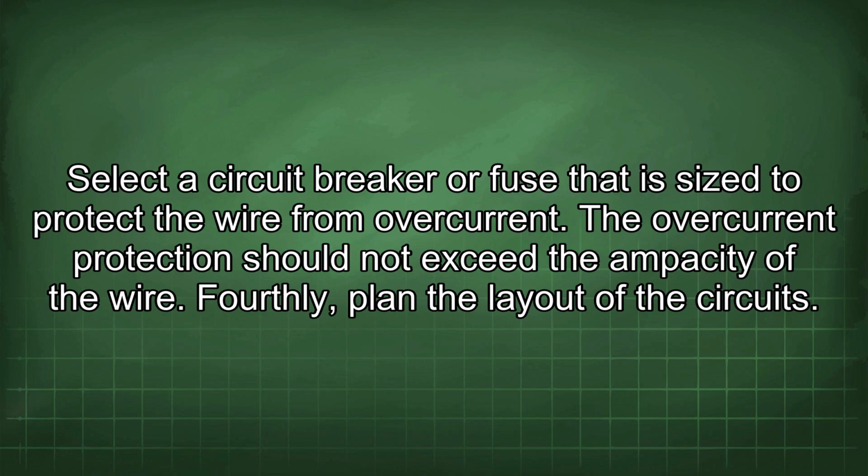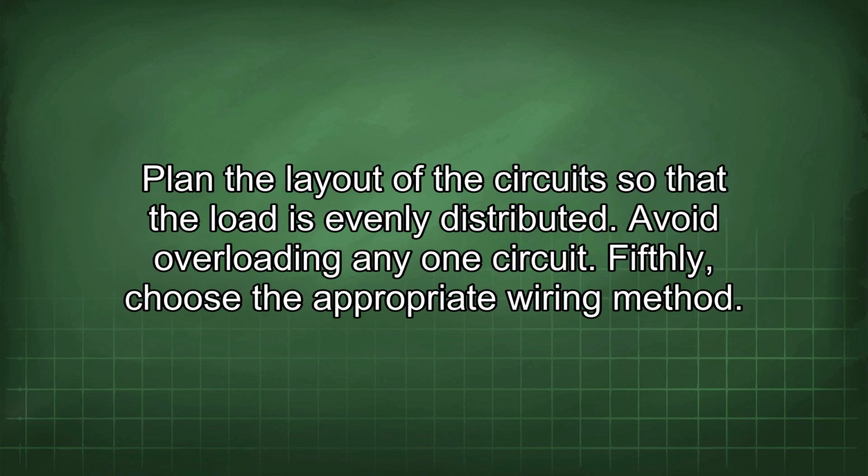Fourthly, plan the layout of the circuits. Plan the layout of the circuits so that the load is evenly distributed. Avoid overloading any one circuit.